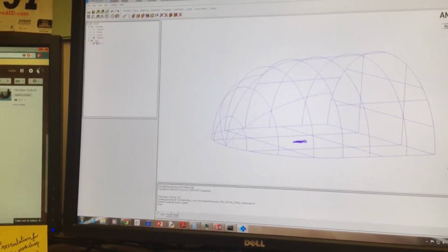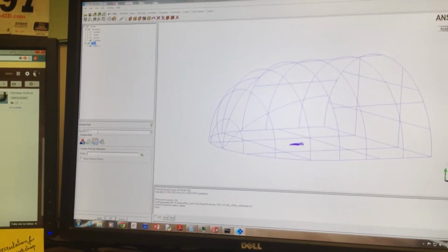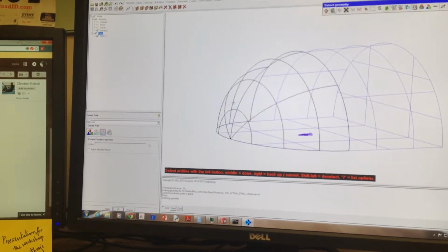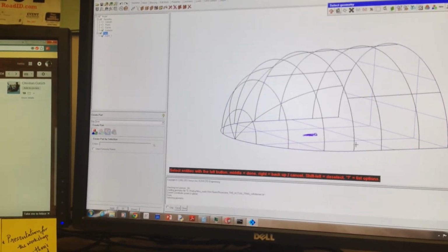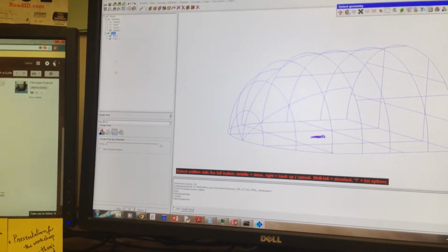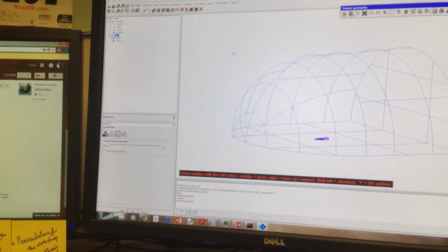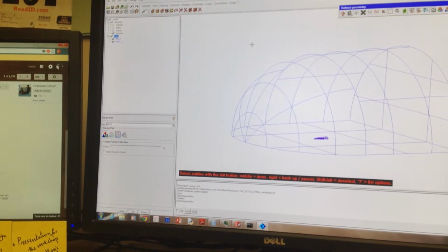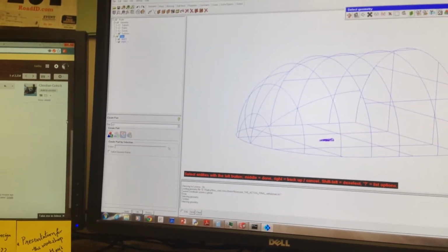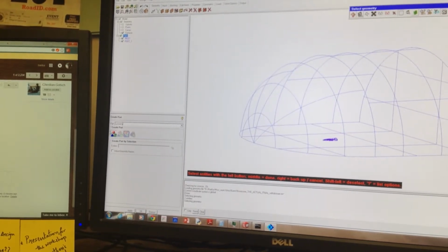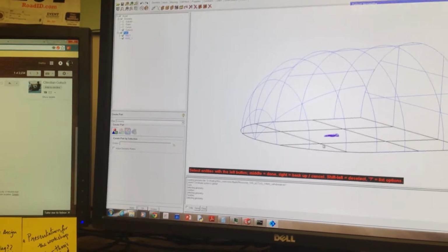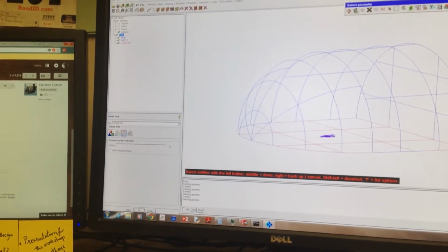Surfaces. Okay. Create part inlet. Select the inlets. That's it. So create a part, inlet. When you're clicking, click the wheel button for apply, or you can click apply over here. Click on the part, click the middle wheel button, or you can just directly put apply.